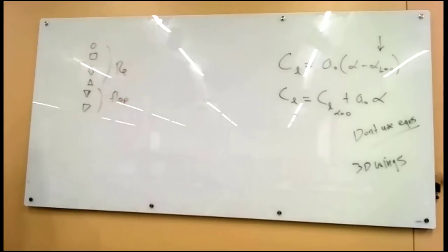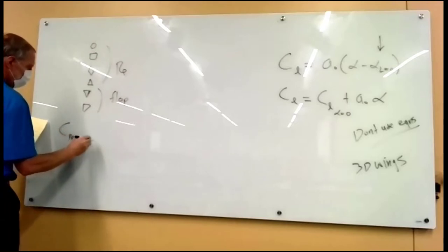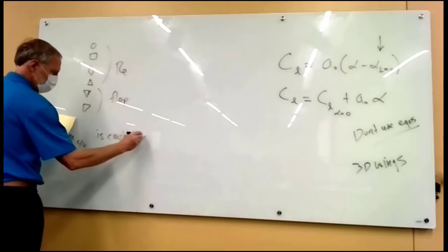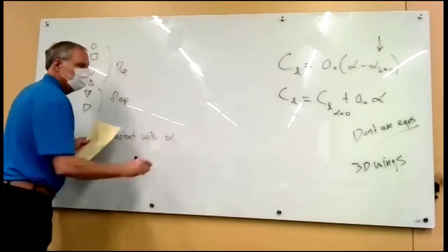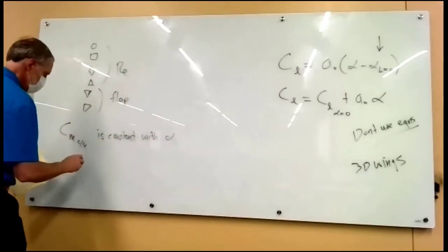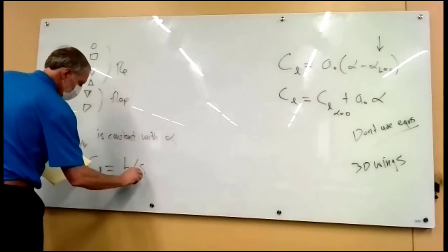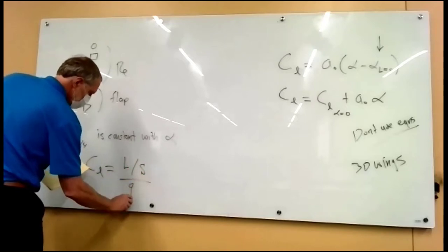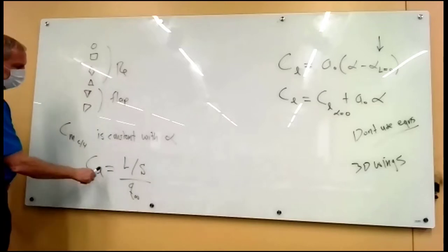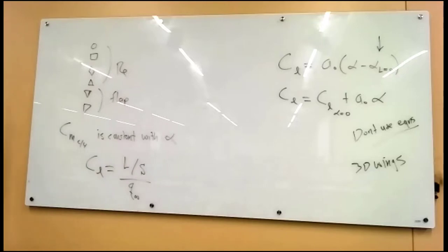So you have to find the right symbol. The pitching moment about the quarter chord point really is constant with angle of attack change. And we need to talk a little bit about the definition of lift coefficient for an airfoil, because we defined CL as the total lift divided by the area times Q infinity.